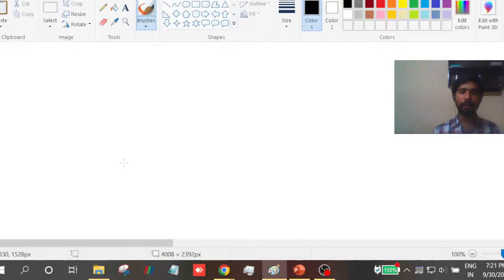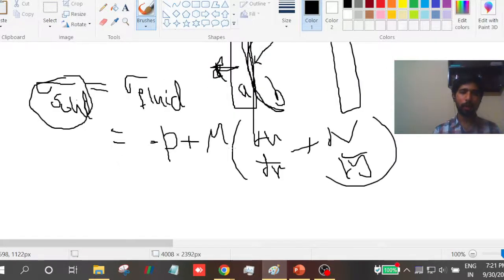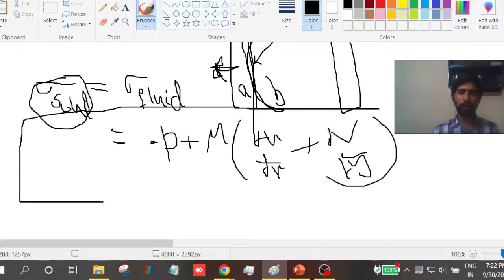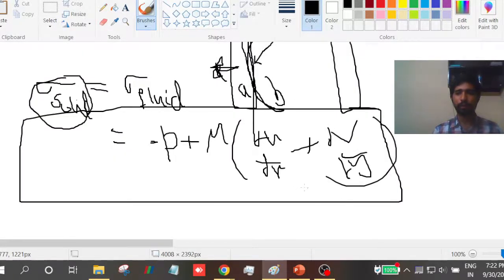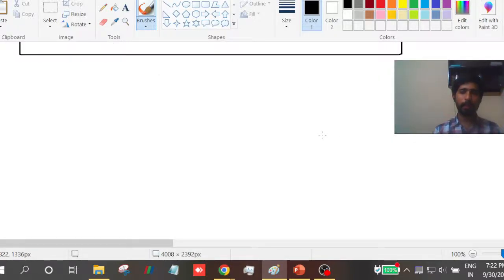But as I said, in the one fluid approach, these things are included as a source term only. Mainly there you will have the surface tension force instead of this pressure force which comes into the picture for fluid structure interaction. So that is the main difference which you observe. I have just tried to give some analogy between the various multiphase modeling approaches.